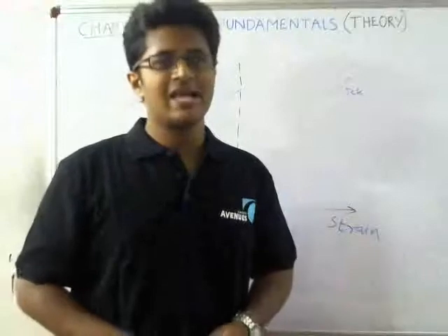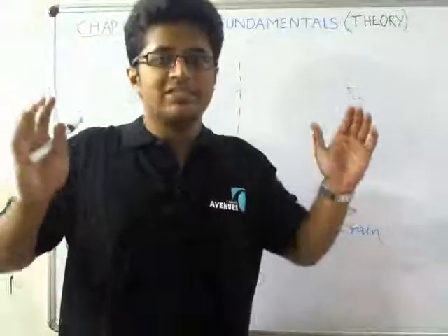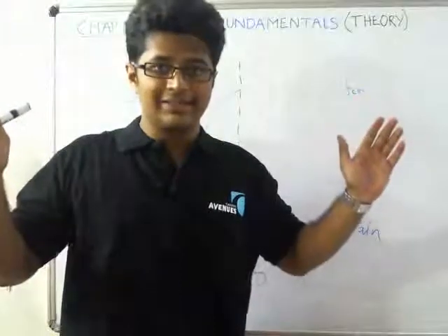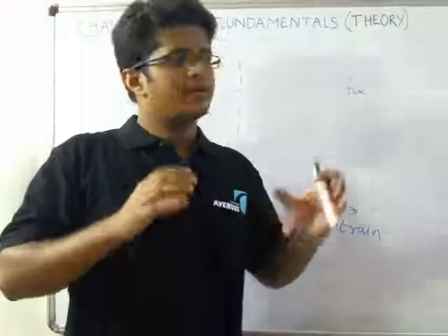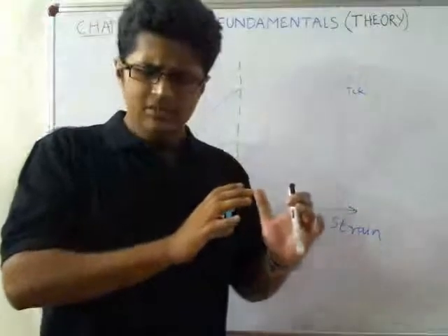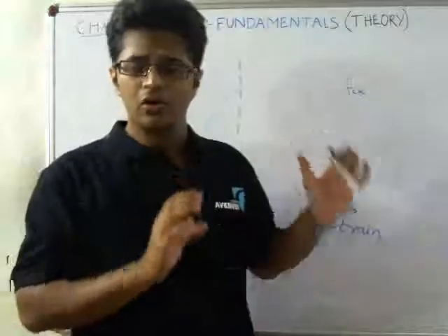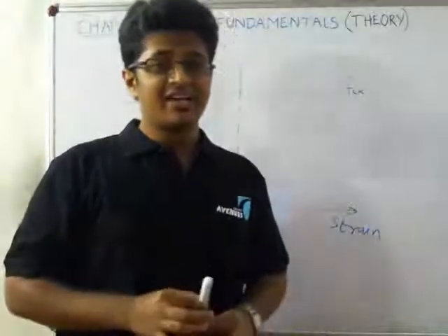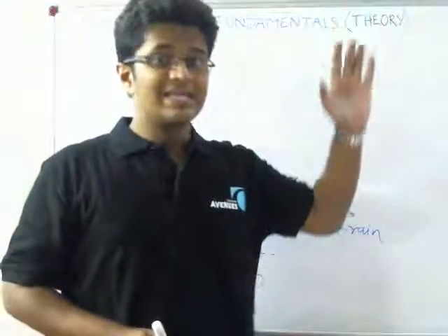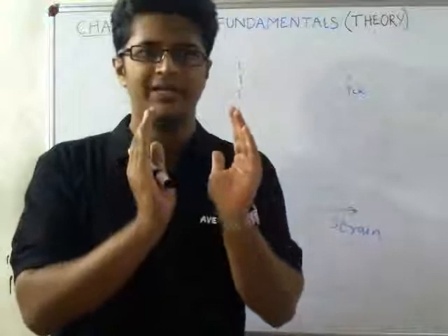So what happens is, as the concrete volume increases, or I would say the slenderness ratio increases, in comparison to the 15 centimeter by 15 centimeter cube, the volume of the beam or the column is very huge. So the FCK value of the beam is less compared to what we get in the cube test.